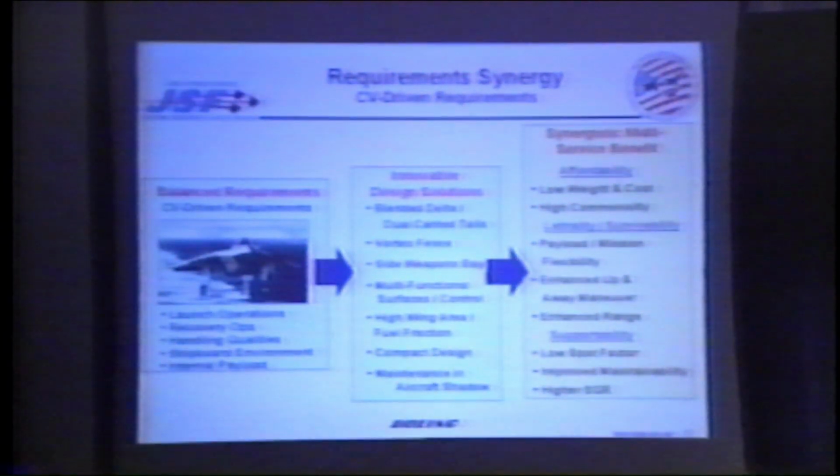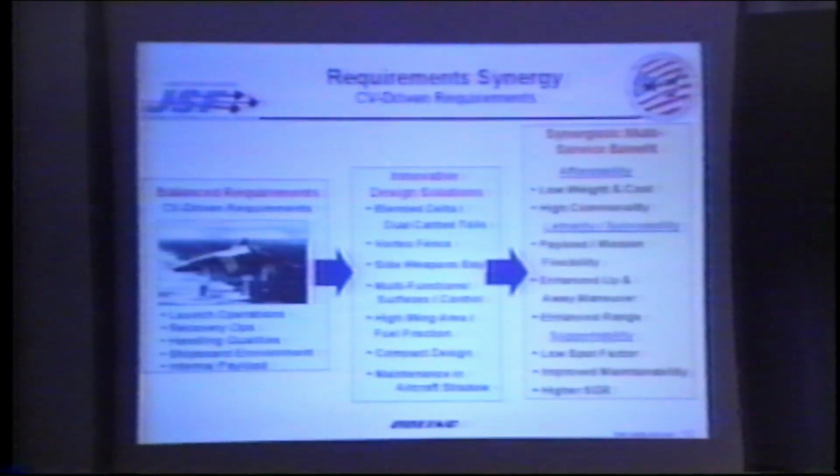device is it allows us to have a common wing area for the naval version as what we have with the conventional takeoff and landing version. So that vortex fence gives us commonality in terms of wing plan form for the CV and CTOL variants. That commonality in terms has major cost benefits across the services.